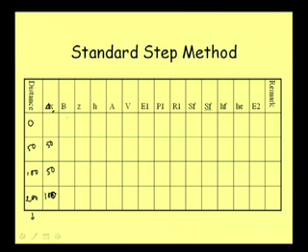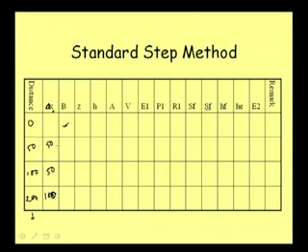Then we can put what is our bandwidth B. Again, if it is a non-prismatic one, then the bandwidth from 0 to 50 and the bandwidth here may be different. So, that way we can write the bandwidth value. I am not putting any value here. Then similarly Z, based on the bed slope and this distance, we can find out what is the rise of the bed or what is the fall of the bed, that Z value we can write. So, Z1, Z2, all this we can write.